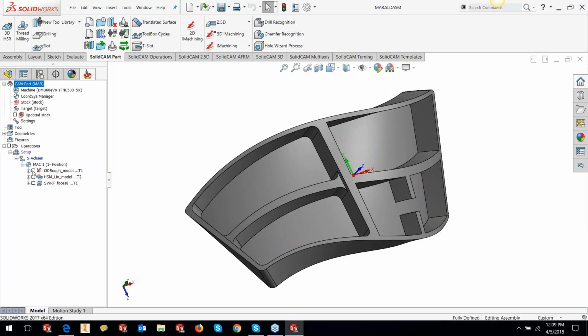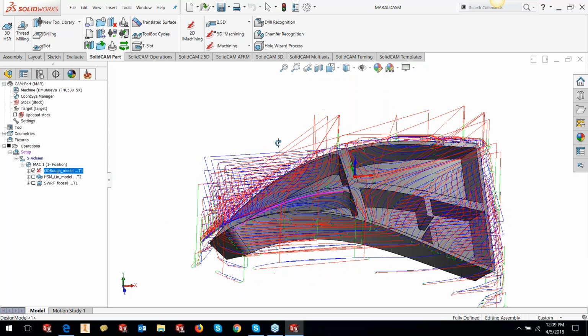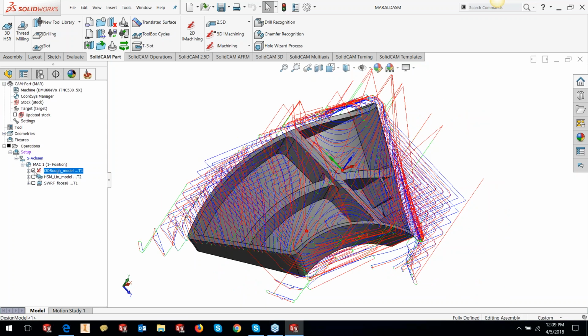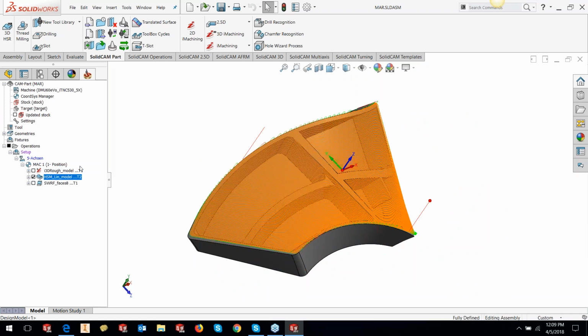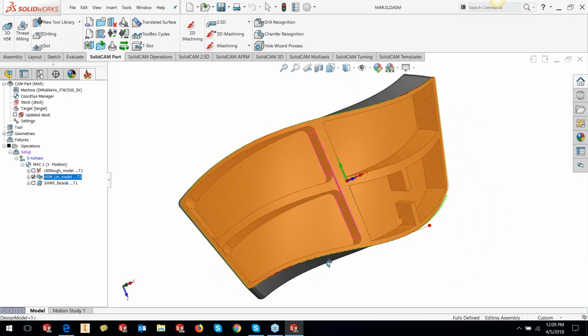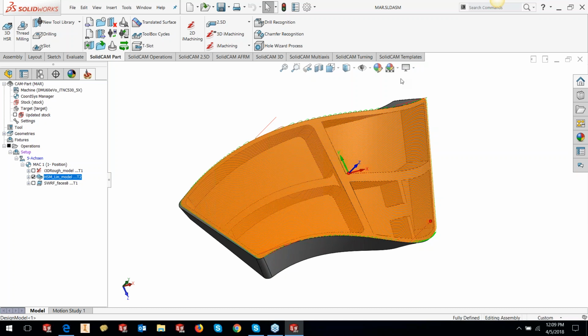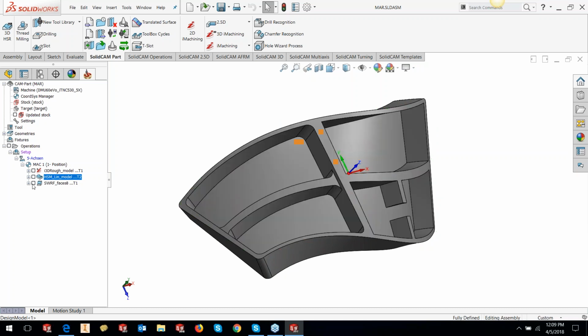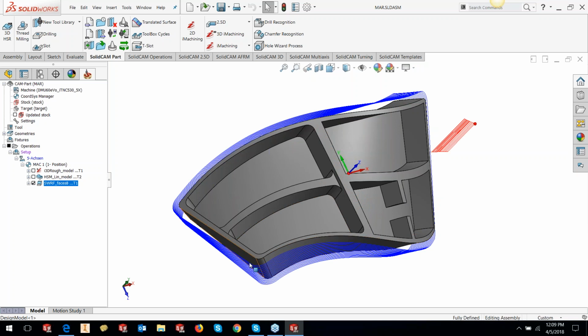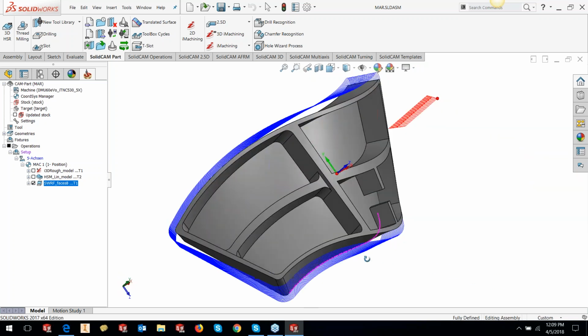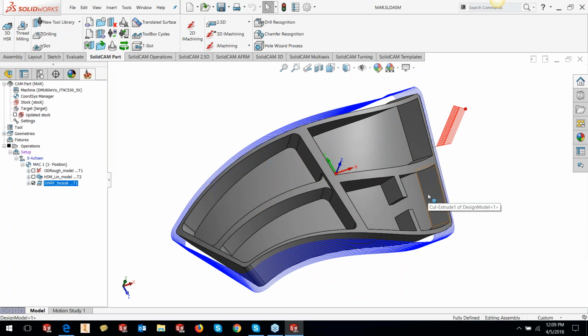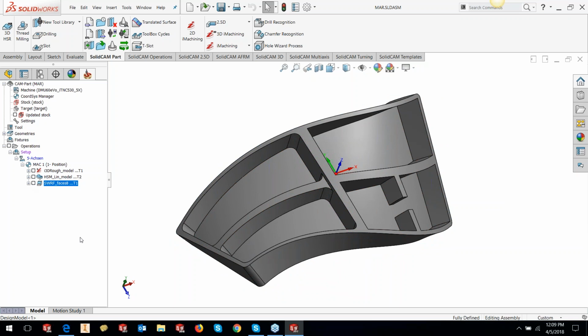In this part, what I've done is I've done the iMachining 3D to remove the material. And then I've closed the top to generate an HSM linear machining to just make it ready for multi-axis roughing. And then I've generated the swarf surface on the side, where the side areas are completed. So I have got a block that looks almost like what is seen on our screen, except that there are no pockets generated. And these pockets, along with this cutout, will be done in multi-axis roughing.